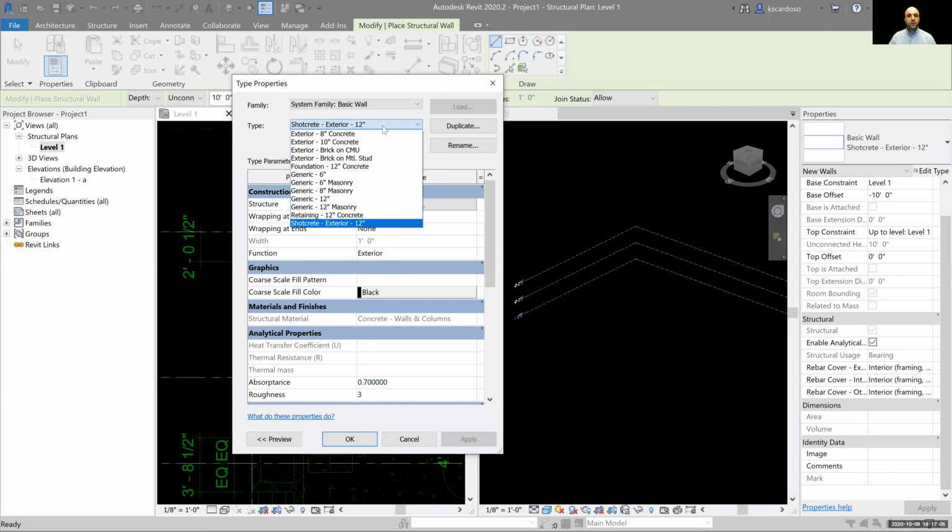So when you're creating your walls, these are some of the defaults, but try to get specific with where they should be used, okay? Because not only will that help you out later when it comes to creating schedules and pulling quantities, but it's also a training tool for less experienced staff. Hey, have you updated your walls yet? Oh, well, what are they supposed to be on the exterior? Well, how is it supposed to be built? And then that's an opportunity for training, right? So in the template you're using, these are just some walls that I've created.